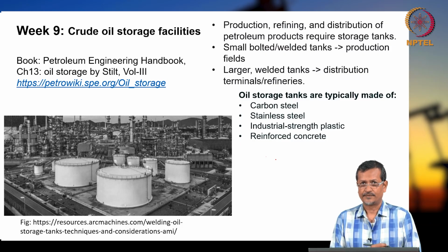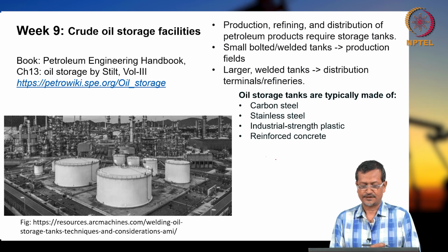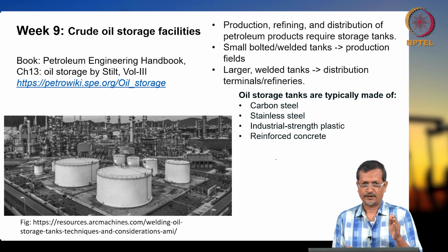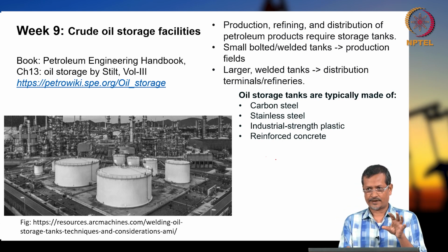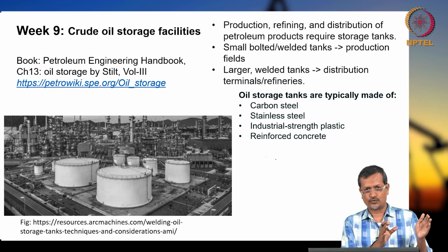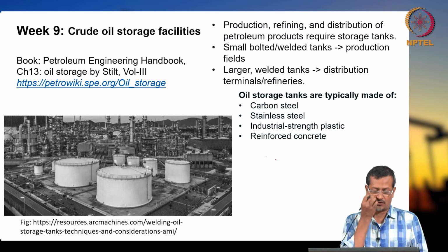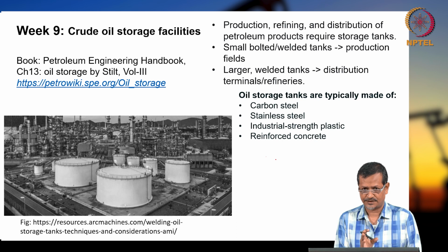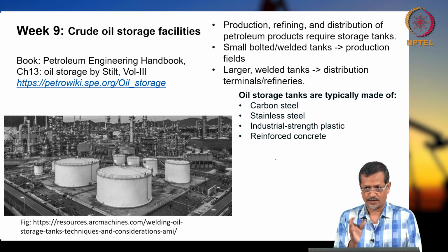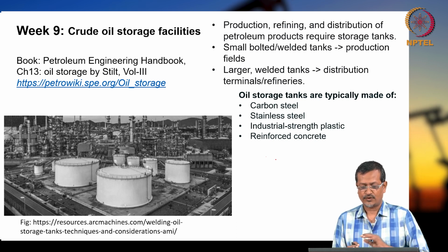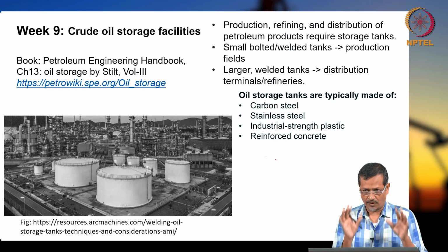Good morning, everybody. In previous lectures, we have seen how to separate oil, gas, water, and sand. Whenever we get an oil, water, gas mixture with sand, we pass the fluid through separator systems. Maybe a vertical separator or horizontal separator, then gas separation separately, a gas treating system such as an amine treater, or water removal systems. From the oil also there will be a water removal system, sand removal system, and water disposal system. After doing all those things, you get pure oil, or crude oil.